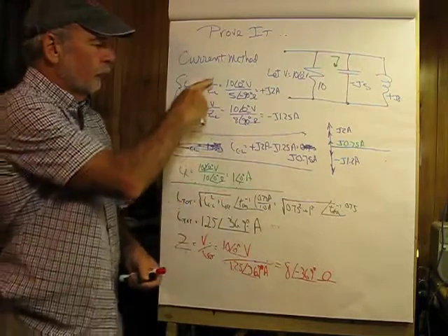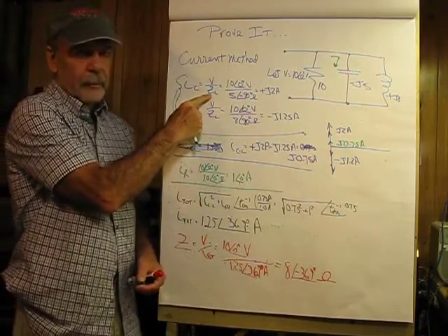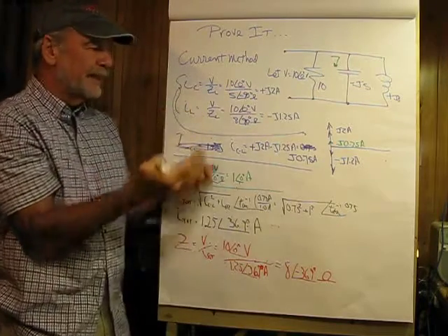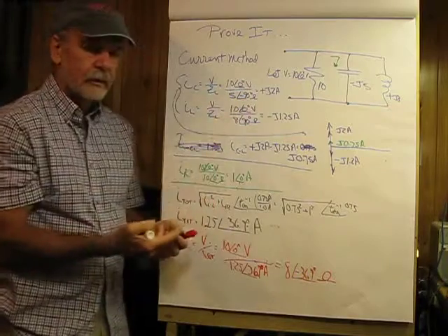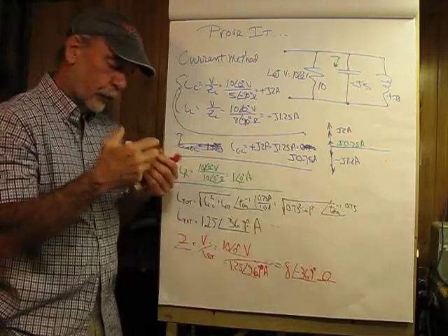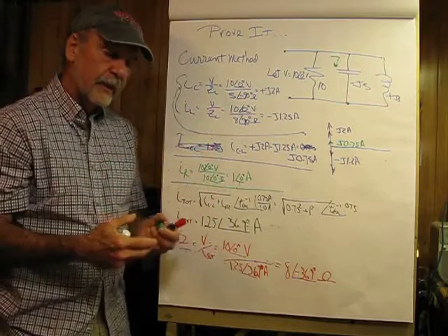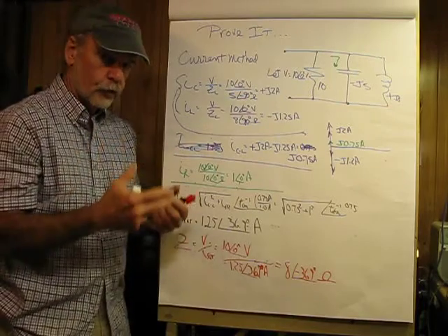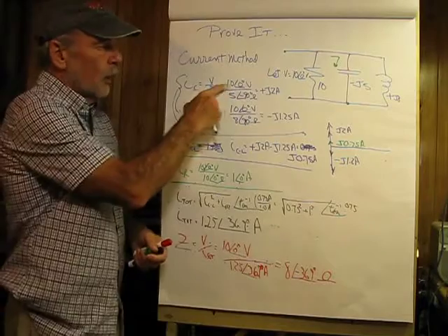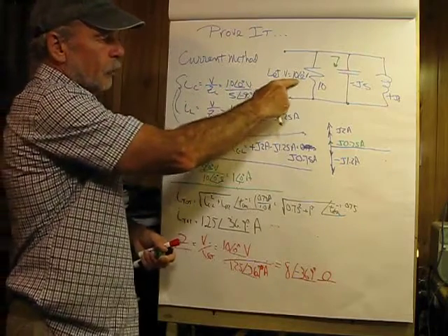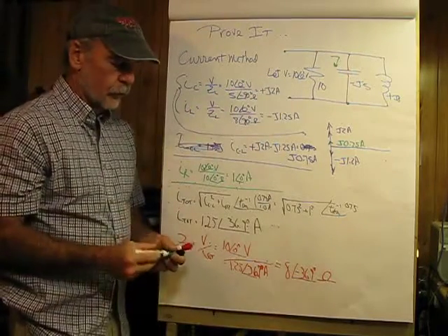That would be equal to the voltage divided by the impedance of the capacitor. And when you say impedance of a capacitor, that means magnitude and direction, whereas the term capacitor reactance infers only a magnitude. So I'm letting V equal 10 volts at 0 degrees here.